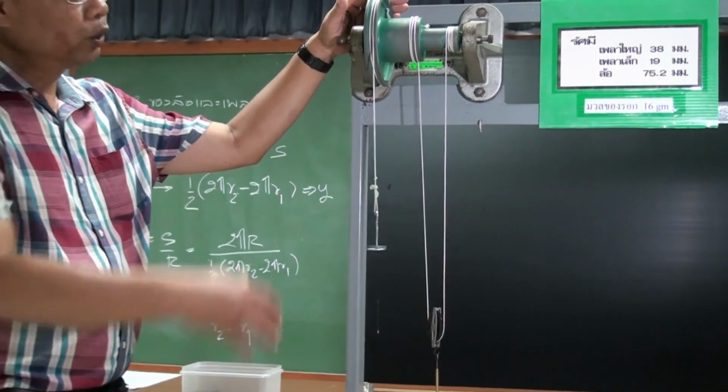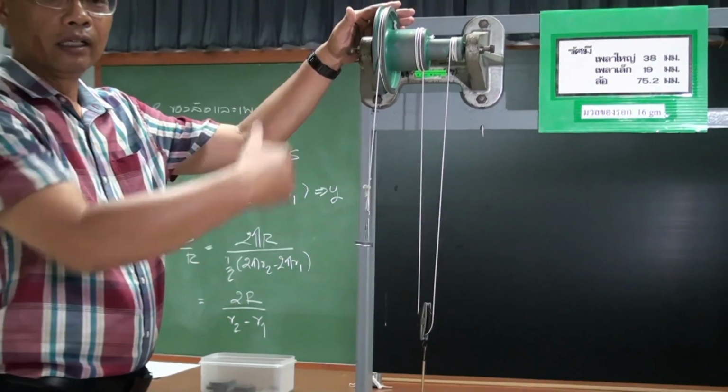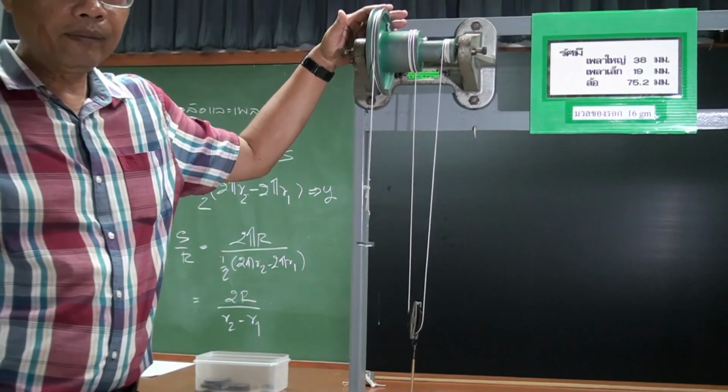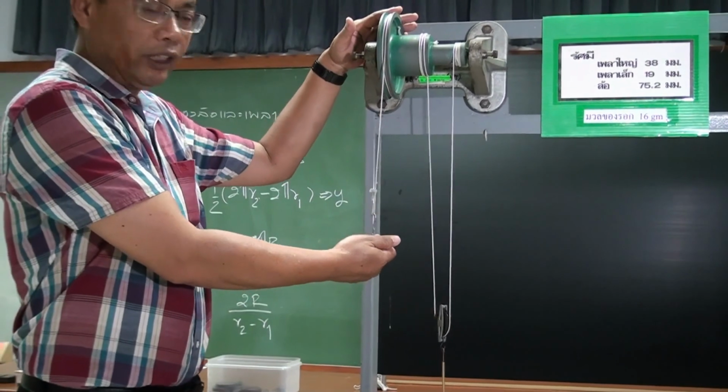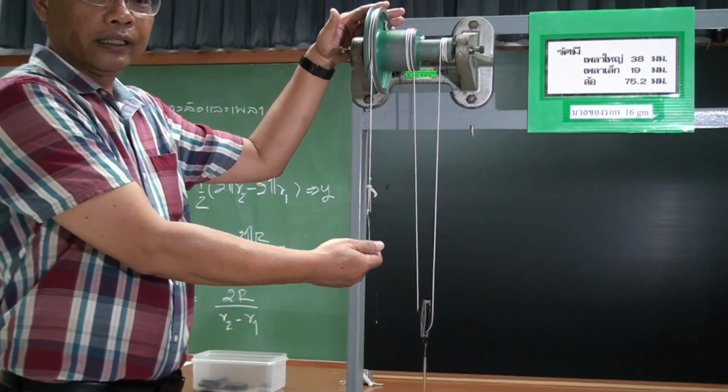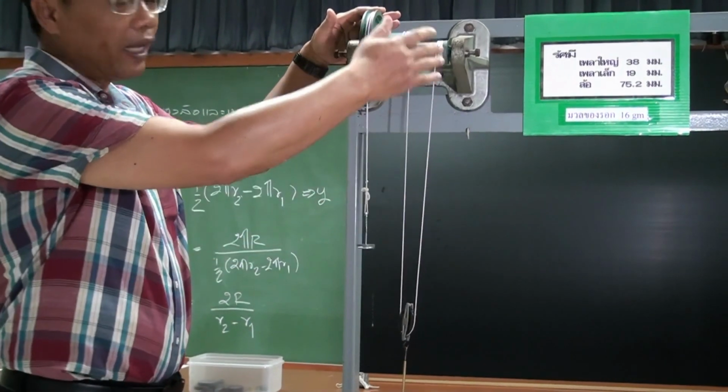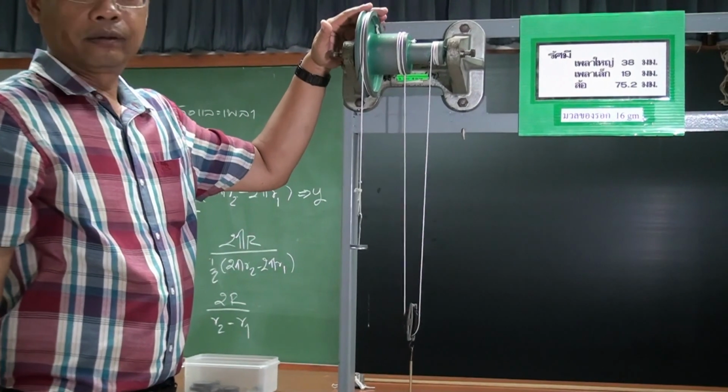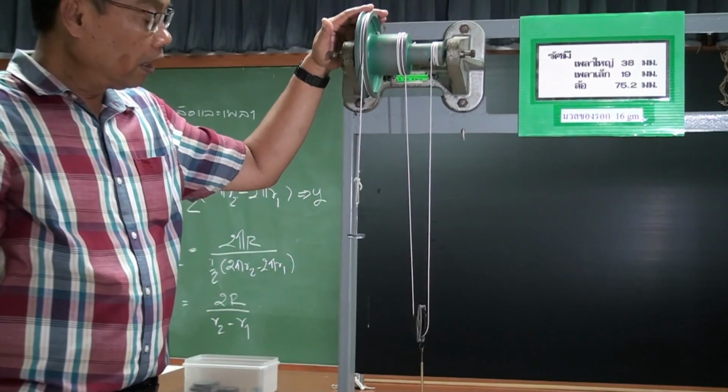Again, be sure to record the F and the W just like last time, and use the F, the W, and the velocity ratio that you have in order to calculate the friction and the efficiency of the system based on the equation that is given in the lab manual.